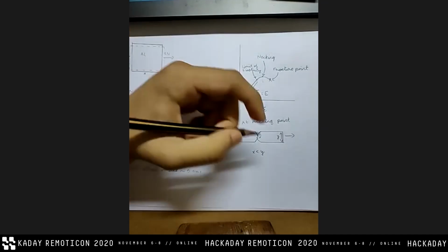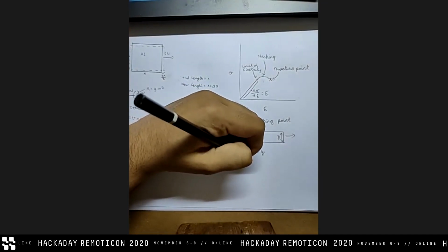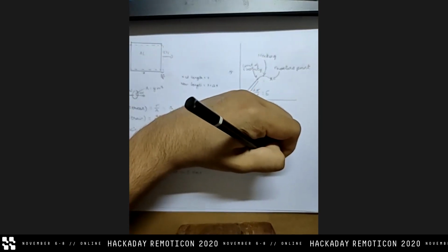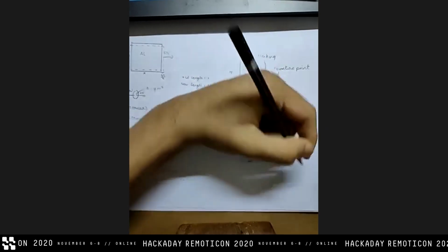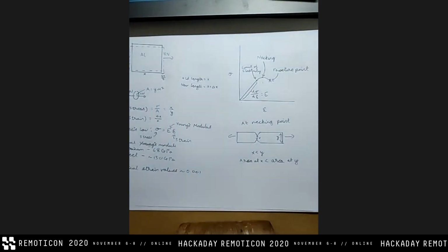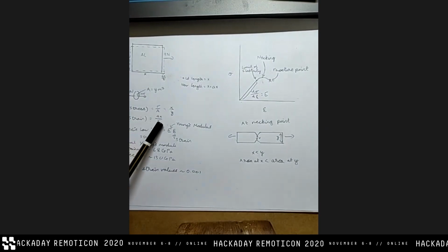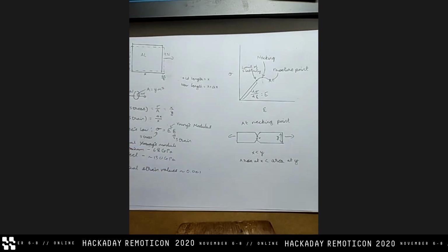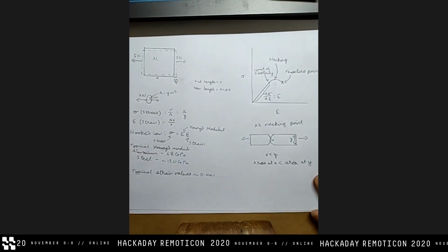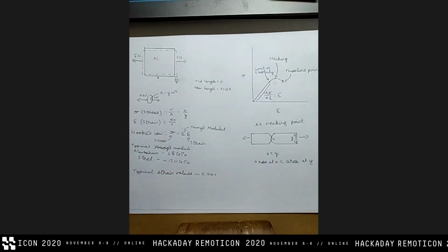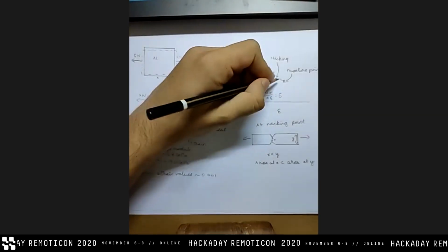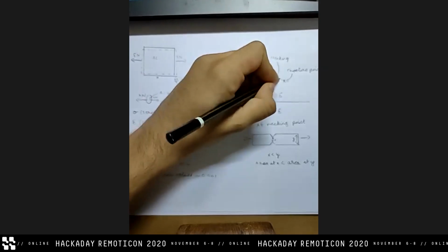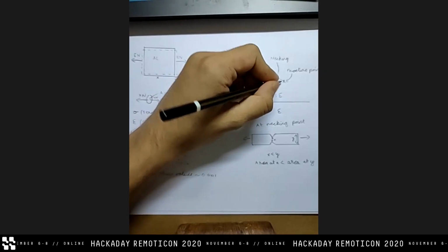And what that means is that the area at X is less than the area at Y. And since we know that stress is force upon area, if you're decreasing the area, you're increasing the stress. So you actually have a higher stress even though the force remains constant. That's why you get this point where even though your force is staying constant, your stress is actually increasing. And that's why you get to here where you need to decrease the force if you want to prevent it from fracturing.